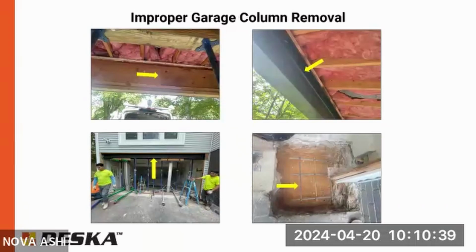Sleeping areas can be less depending on the municipality. If you have an attic, is it an attic with storage or without storage? There's different factors that the building code specifies. And then the same with the roof. The slope of the roof can affect it, as well as the type of roof. Is it asphalt shingles, clay, cedar? They all have different weights to them.